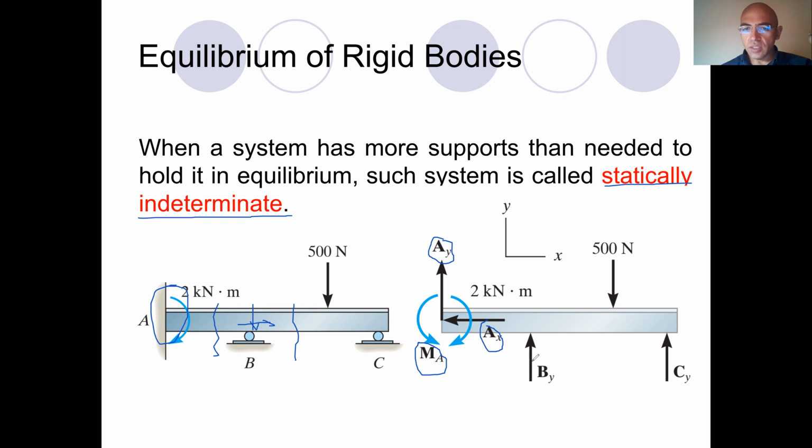As a result, there will be a support reaction coming from the ground or whatever it is at point B. It is the same for point C. If you isolate the part of the object there, you can easily say that it will not be able to move downwards at C. As a result, we have some normal force component coming from the support at that location.